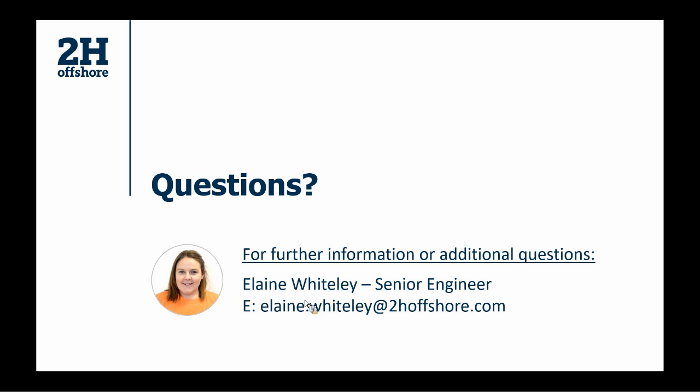If it shows that, yes, the problem is significant and that in its current state the system is not acceptable, then remediation work would be required, but that would be very dependent on what the integrity issue was that you saw. So on the very first slide, you saw the picture with the centralizer missing. Below that, there was a couple of pictures of a conductor with a sort of lightning bolt shaped damage to it. And underneath that, there was a stress plot from local FEA analysis.